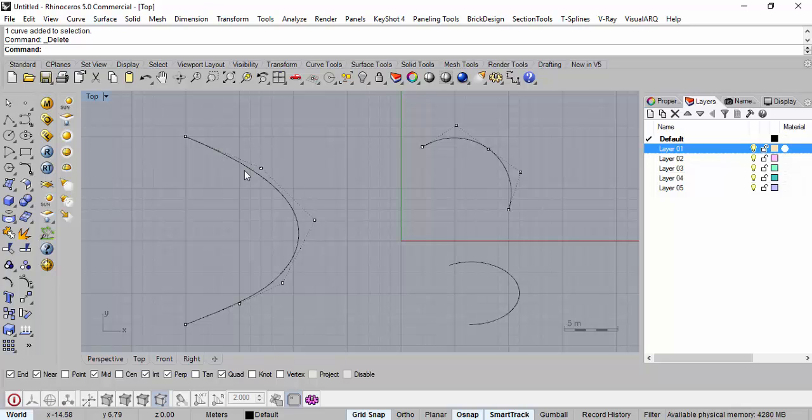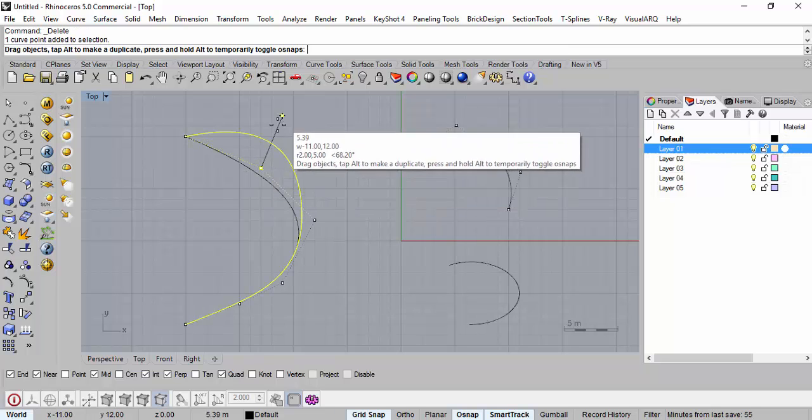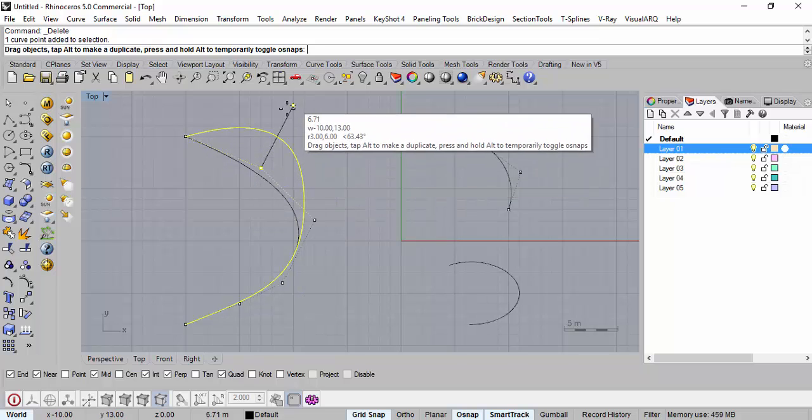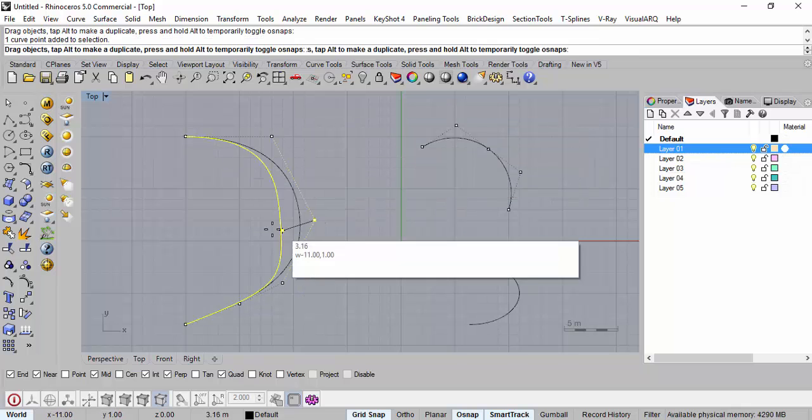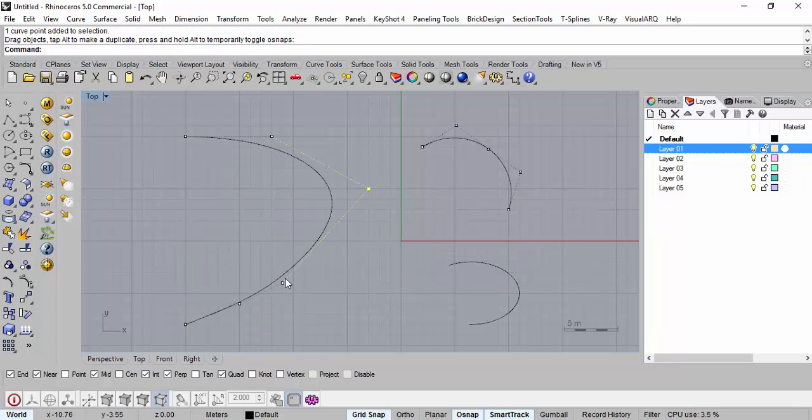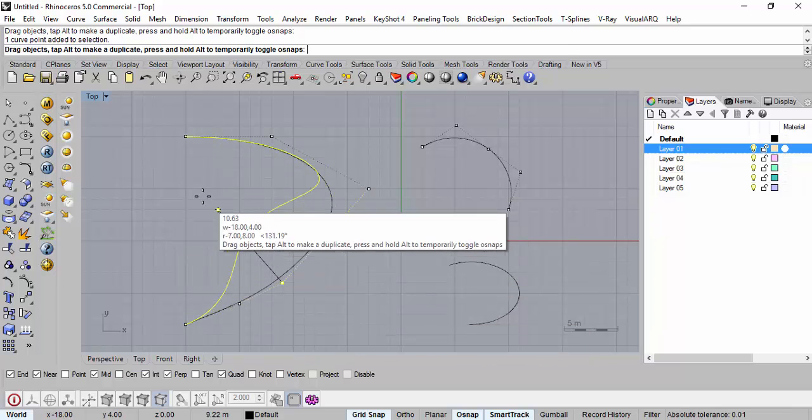then those can be drawn only through a mathematical calculation function, and people have worked on it and it has come to be known as Bezier splines. It's similar to splines which you are aware of. This Bezier word is very common if you're using Photoshop or pen tools in Photoshop or CorelDRAW, wherein this curve is dictated by the control points. If I hold on to this control point, you can have any bulge, any shape, right? The curve doesn't essentially go through it.